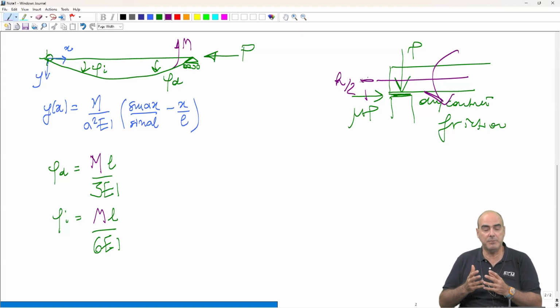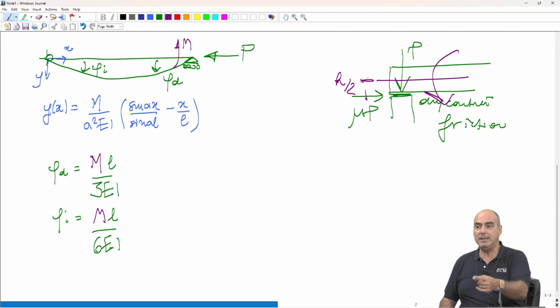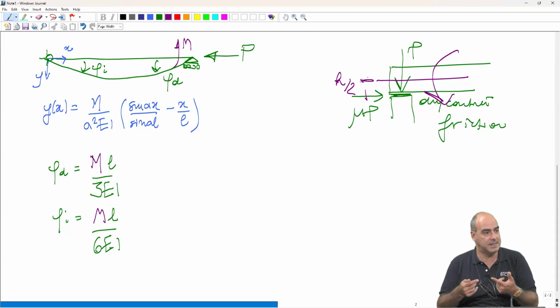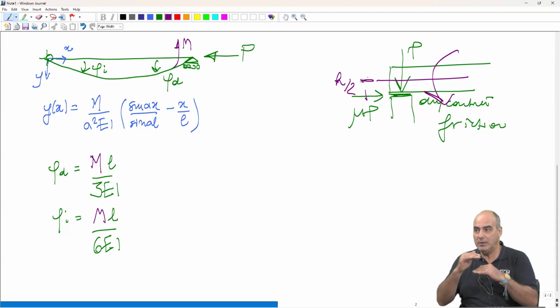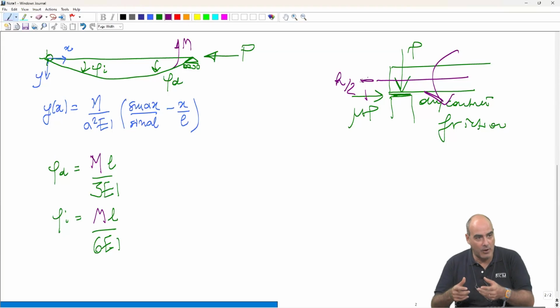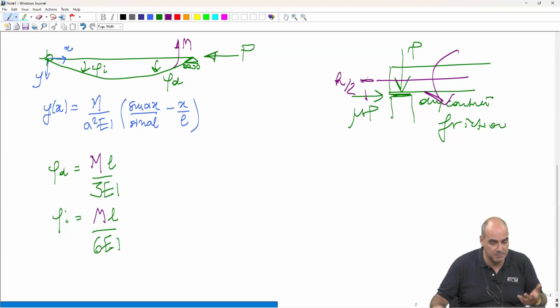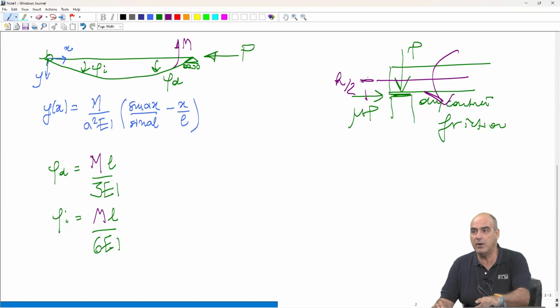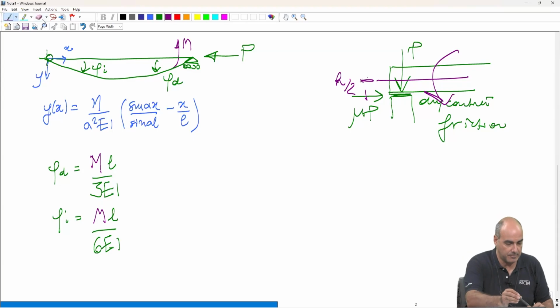In a steel structure, because of bolted joints, if you have designed your bolted joint as a hinge and you have additional bending moments, generally the bolts are really designed to their limit. So if you start losing one, you overload the others and you can lose them. There have been cases in which steel structures have failed because of parasite moments in the joints due to restrained deformations.